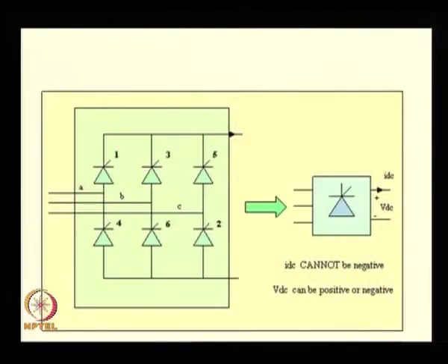If you look at what needs to be done in a typical excitation system, it is to have some kind of continuous control. We did not have it in the demonstrations I showed you so far. In fact, you can see that there is no continuous control. I had to manually adjust the field voltage of the excitation system. This is not desirable because load could change suddenly and then you may have a sudden dip in the voltage. So, you always need to have the excitation system in continuous control mode.